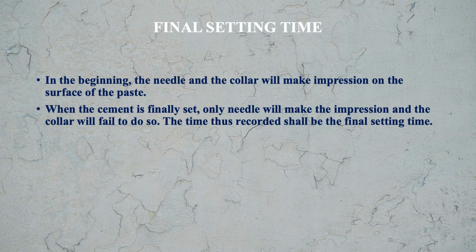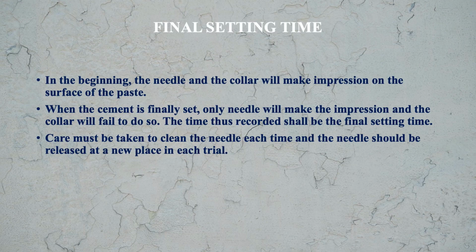So this time we will call the final setting time. Now care must be taken to clean the needle each time and the needle should be released at a new place in each trial. That way we do the final setting test.